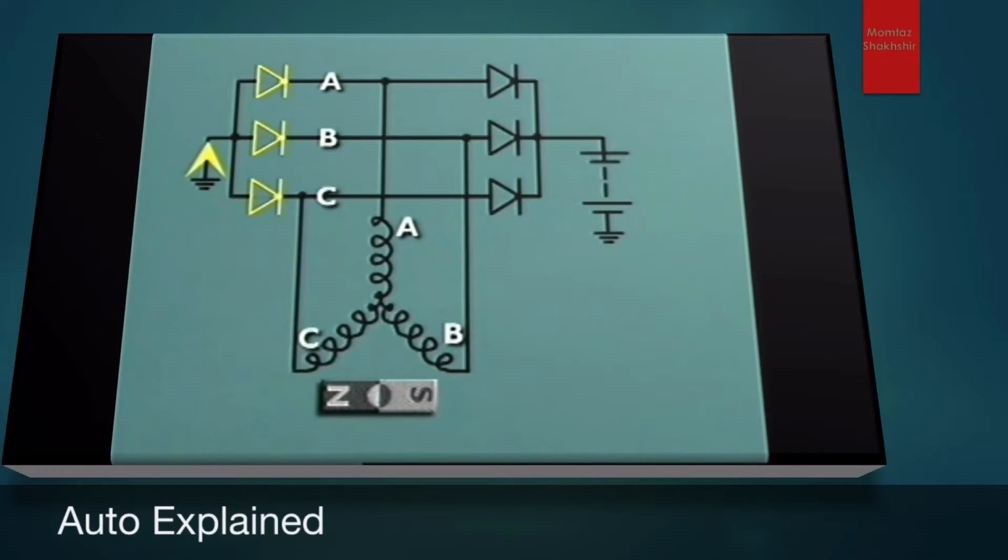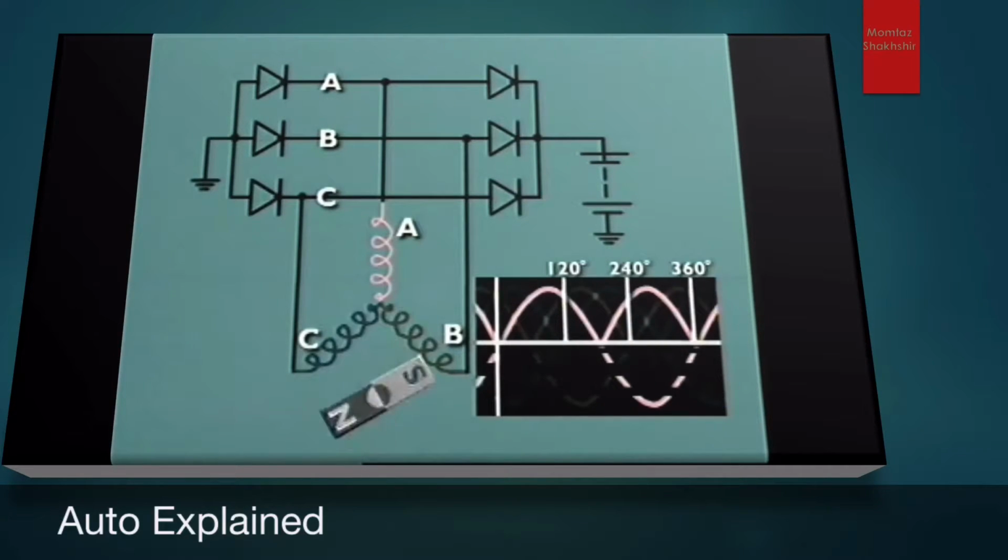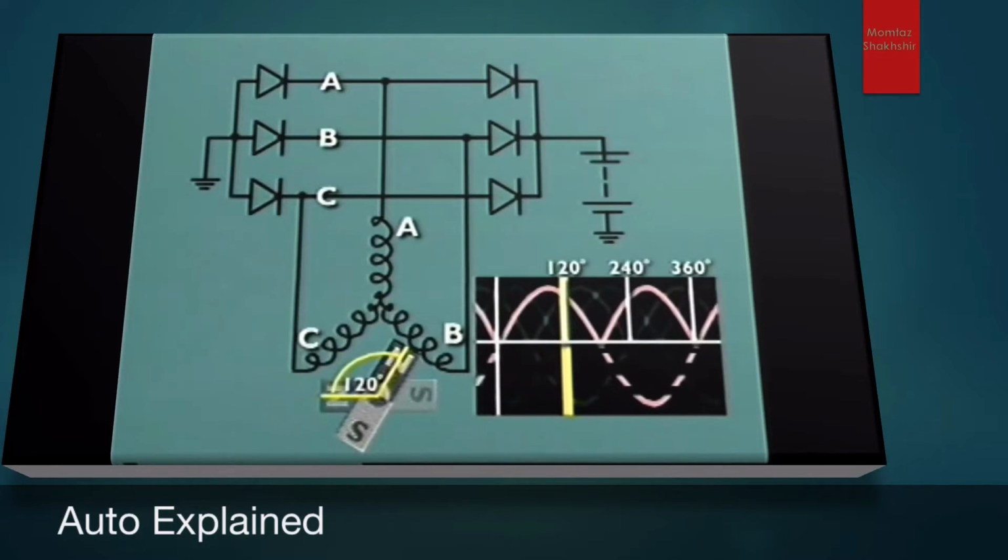In each revolution of the magnet, the polarity of each phase winding changes, and as a result, the current changes direction. To provide a unidirectional or DC output, a complete circuit is needed for current to flow when each change in polarity occurs. Let's look at the action of just one phase. As the rotor turns, it induces a voltage in the winding, which generates current flow. In this position, and with this polarity, the current path is as follows.